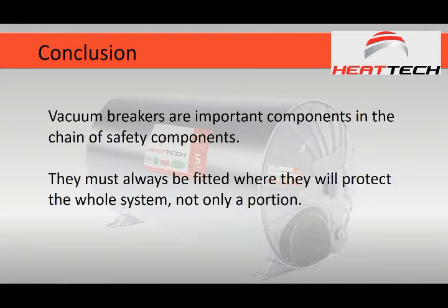Henry, he says, I've never seen an install like this over all my years as a plumber. And you know why you haven't seen it like that? Because 90% of the time, the highest point in the house is the geyser. So therefore, your vacuum breakers are always on the highest point on your system, and that's why you generally don't see it.